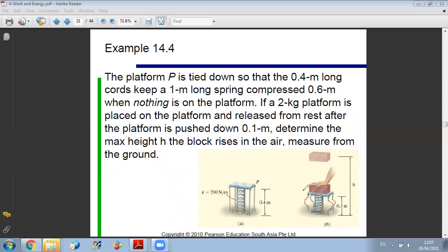Now there are two stages, right. In the first stage, when it is on the plate, there is the weight and the spring. As we saw, from delta L2 to delta L3 nothing changed, so the spring has no effect, meaning only the spring will work from 1 to 2. Okay, so now we can write that between 1 and 3 we have the work of the weight plus the work of the spring equals 0.